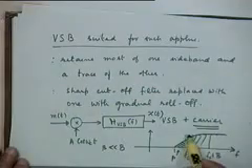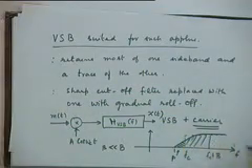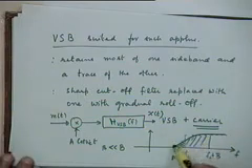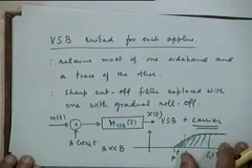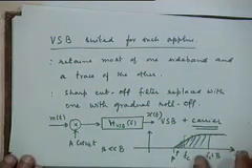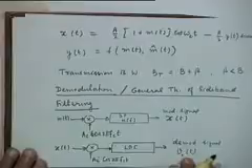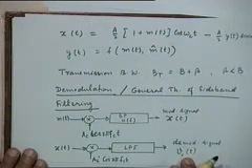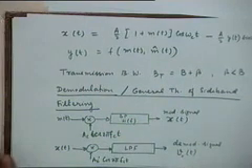I do know that this kind of filter is fine, but is it fine for any kind of gradual, increasing attenuation? That's the basic issue we want to address. What should be the constraint on the filter, what should be the nature of H(f), so that if I do synchronous demodulation there should be no problem and v_o(t) should be equal to m(t). That's the question we are addressing.